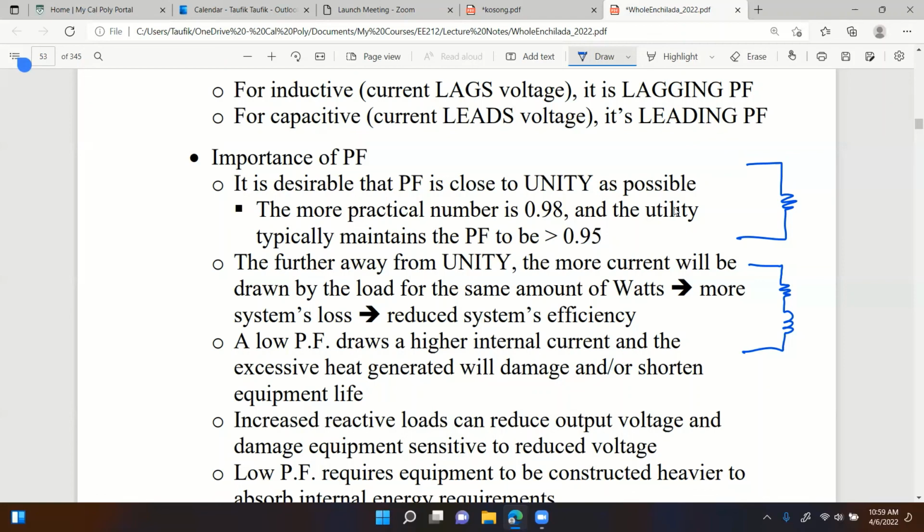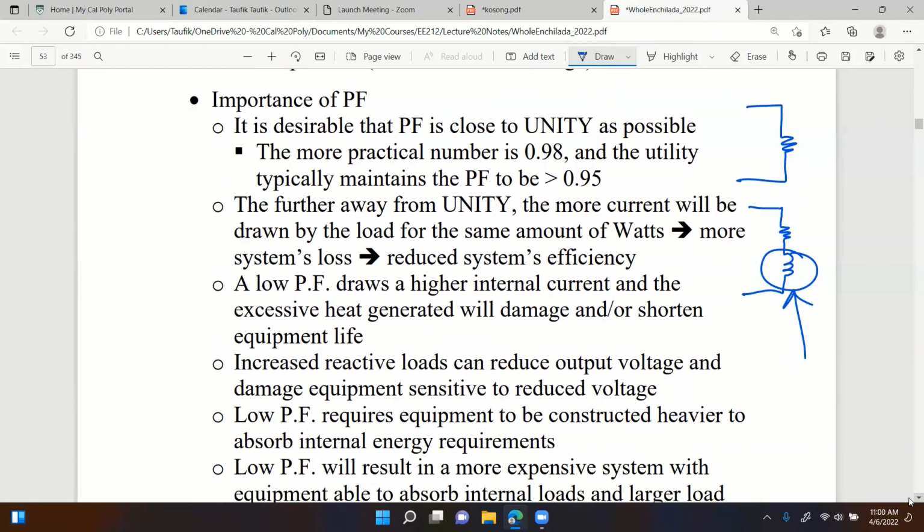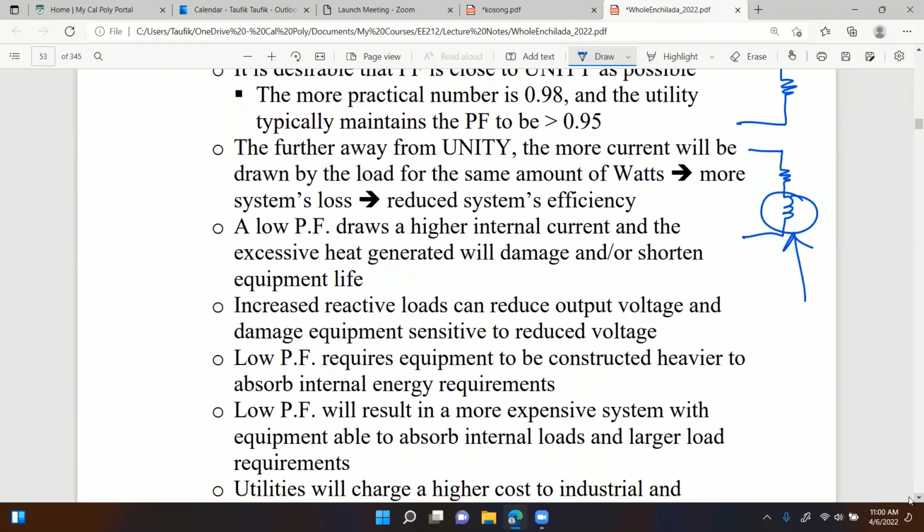Coils, yes, exactly. If you have air conditioning, same way, you have motors inside, that's also coils. Heater, same way. So those are big motors. And that's why it's very common that our house is actually inductive. It's not resistive, it's not capacitive, it's mostly inductive.